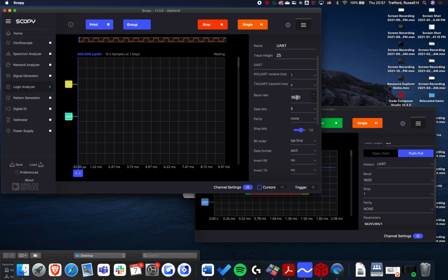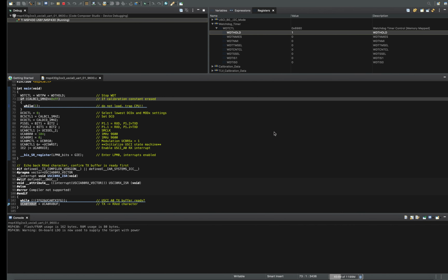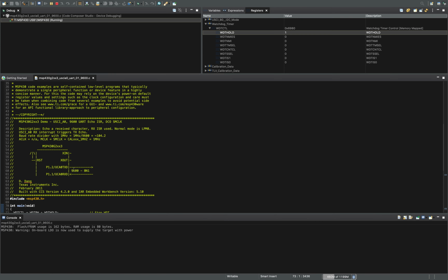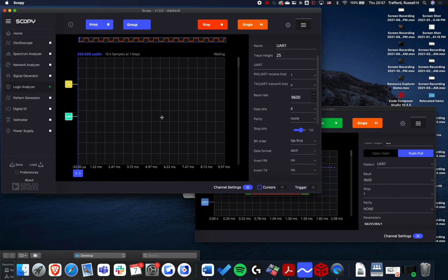Remember that baud rate thing? We need that information. So that 9600, we need that. The data bits is the 8, and N and 1 are all about the parity and the stop bits. So if we go back to the example real fast, when it's talking about all of these settings, 9600, 8, N, and 1, it's talking about the baud rate, the data bits, the parity, and the stop bits.